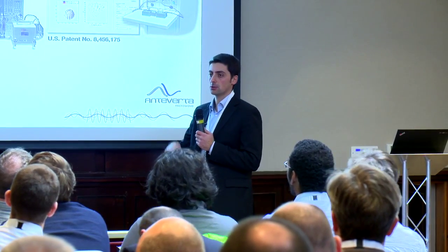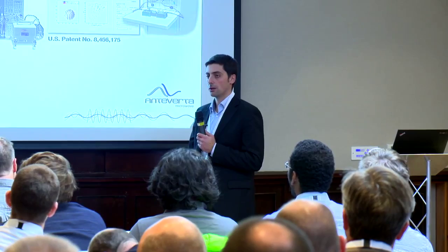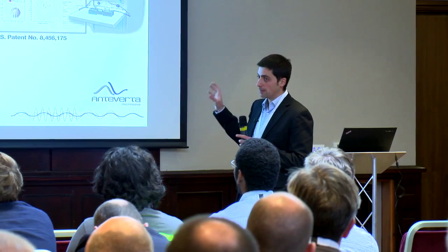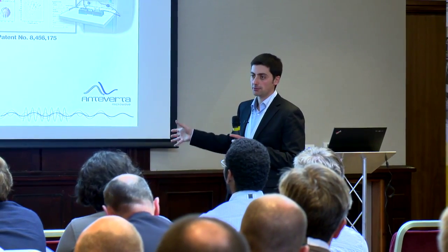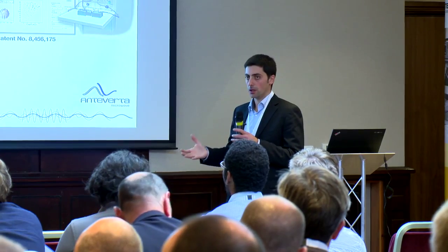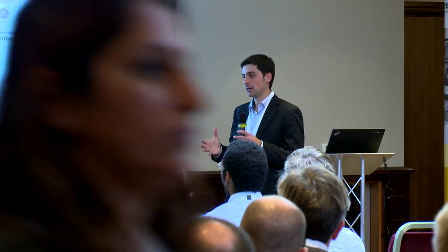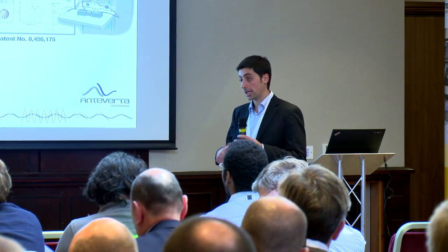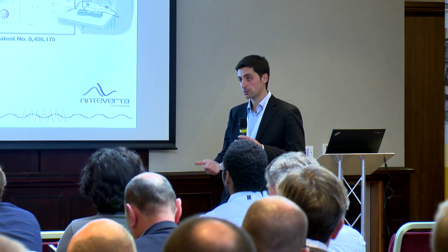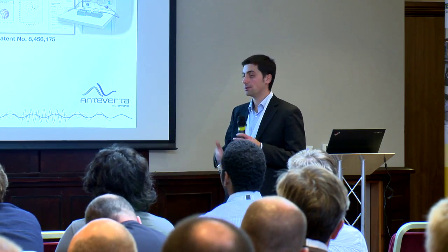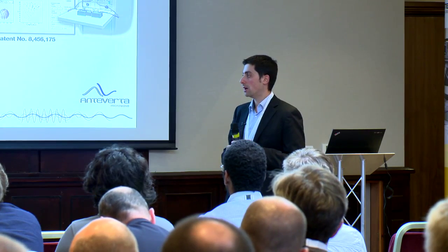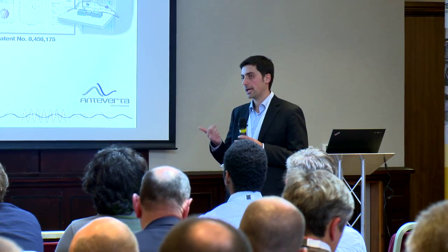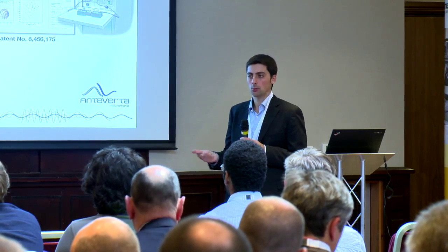So there's a vector receiver solution that's based on PNA-X that is also active, but it's mainly single tone. And the mixed signal load pool is somewhat of a dedicated platform for load pool. So essentially, the two platforms can do most of the same measurements. They can measure nonlinear time domain voltage and current waveforms, both the PNA-X and the mixed signal load pool. They can do load pool in an active way. The main advantage of a mixed signal is that it's faster and that it can do modulated signal load pool.